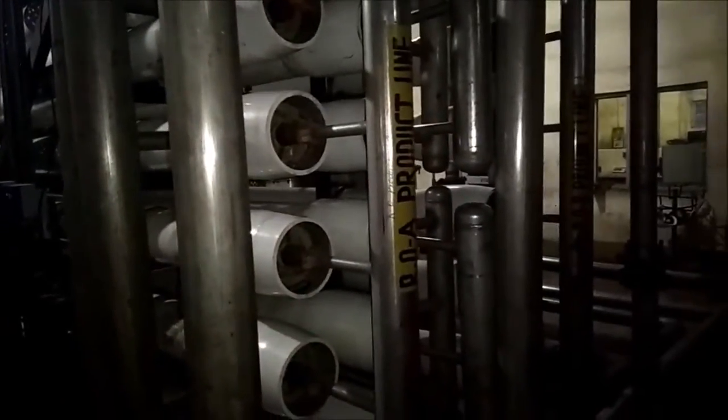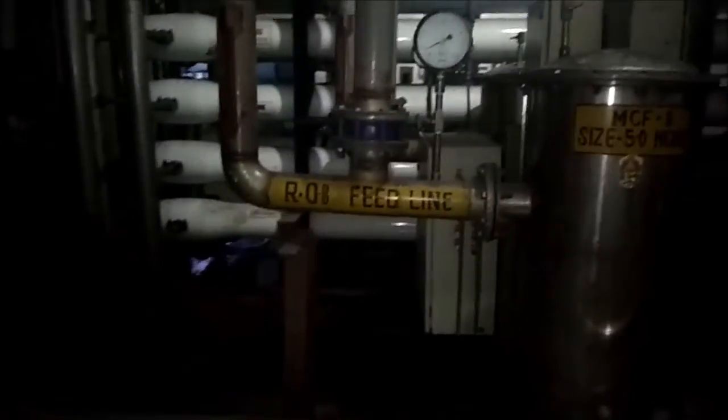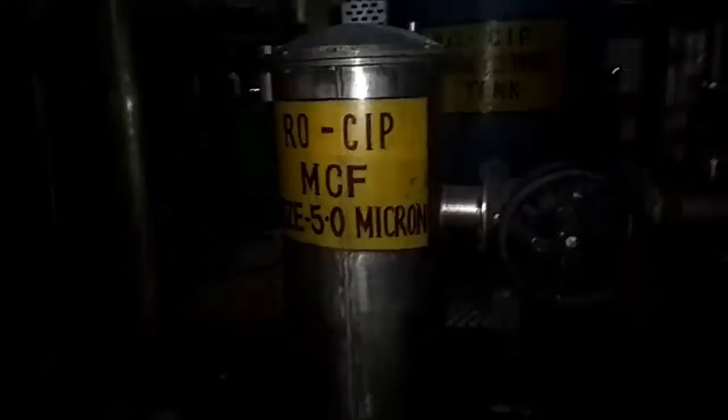And this side over here, this is the final one, the RO, reverse osmosis, which takes out 99% of the minerals out of the water and leaves only 1% of minerals, with a pH value of 6.5, which makes it acidic. And this water is used for the thermal power plant. It goes inside the furnace boiler, the steam is produced, and then it's used for moving the turbines to make electricity. This is the whole last process, the RO, reverse osmosis.